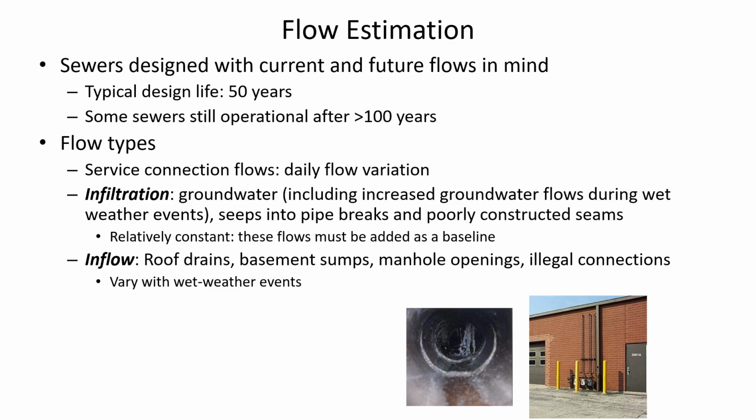They more or less got that sorted out by installing one-way flow valves, check valves, into people's homes that were in those low-lying areas that were subject to backflow. But I think maybe they provided some incentives. They were offering people rain barrels if they disconnected their roof drains going into the sewer. So that's just something you don't necessarily need to have going to the wastewater treatment plant, because there's nothing toxic or dangerous about the flow that's coming off of roofs.